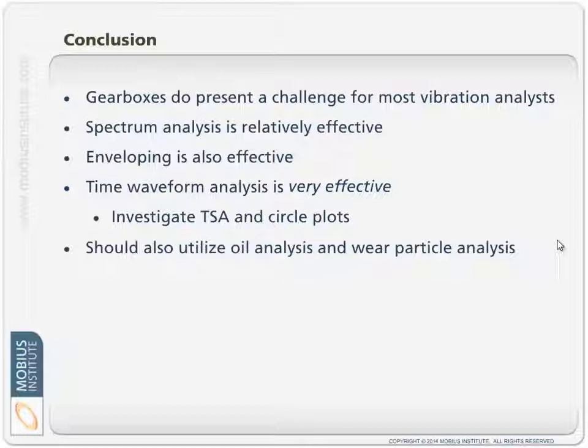A few quick factors. You do have to think about gearboxes very carefully to make sure that where you place your sensors, you're capturing the frequencies of interest, there's a good mechanical transmission path to that point, and that your measurements are being set up correctly. Spectra are useful. Enveloping and the various techniques are useful. Time waveform analysis is very important. Have a look at time synchronous averaging, have a look at circle plots if your software has it. Think about the criticality of the gearbox and how important it is that you get all this right.